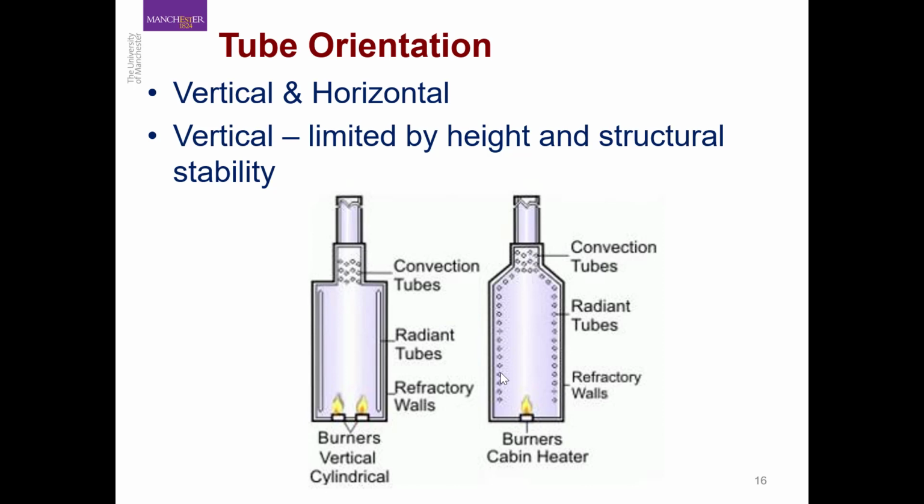While if you are in a horizontal tube, you have a tube filled with water or with the process fluid, and you are heating, and the vapors are being generated in the tube. So you might have a situation where you actually have a clogging effect, where the fluid is trapping the vapors, and as such you can have hot zones developed in the tubes. Okay, that can cause melting of the tubes as well.